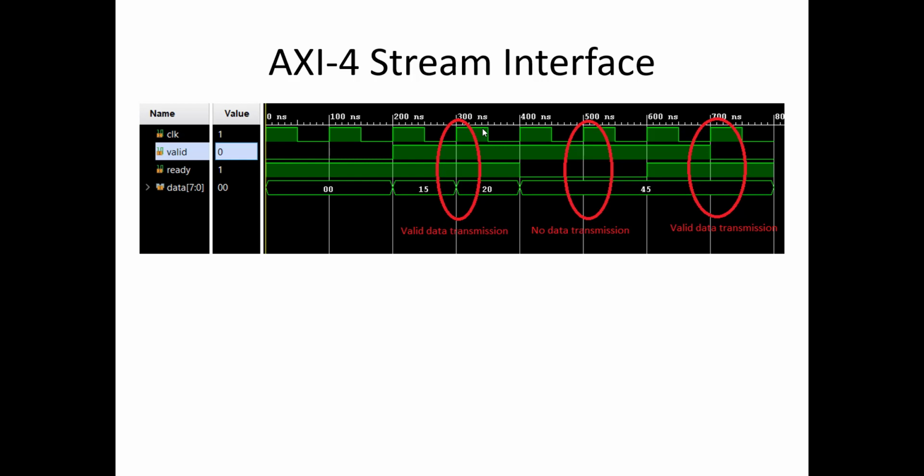But the drawback is, again, this is not memory mapped. So a peripheral which follows AXI4-Stream interface cannot be directly interfaced with the Zynq processor part, PS part, because PS has only AXI4 interface. Whether it is GP port or HP port, they support only AXI4 interface. They don't support AXI4-Stream interface. So you cannot directly connect them. You can connect the stream interface only through some kind of bridge actually. So in our particular case, this bridge will be the DMA controller, which supports